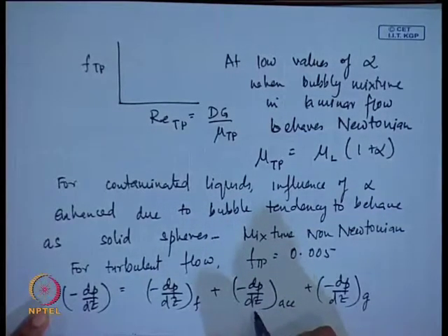Now, we find that usually the frictional and the acceleration components are important at high phase velocities. Whenever the relative velocity is higher, the wall shear stress becomes more important. Therefore, the momentum flux effect as well as the wall shear stress effects become much more important for high flow velocities. Fortunately, under that condition, the flow exhibits homogeneous flow characteristics. So, when the wall shear stress becomes important, when the momentum flux becomes important, under that circumstance the homogeneous flow theory is applicable.